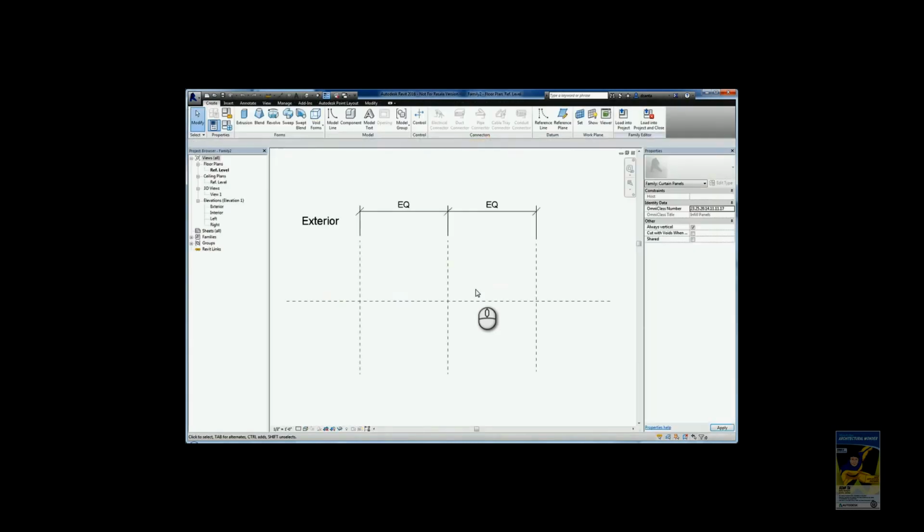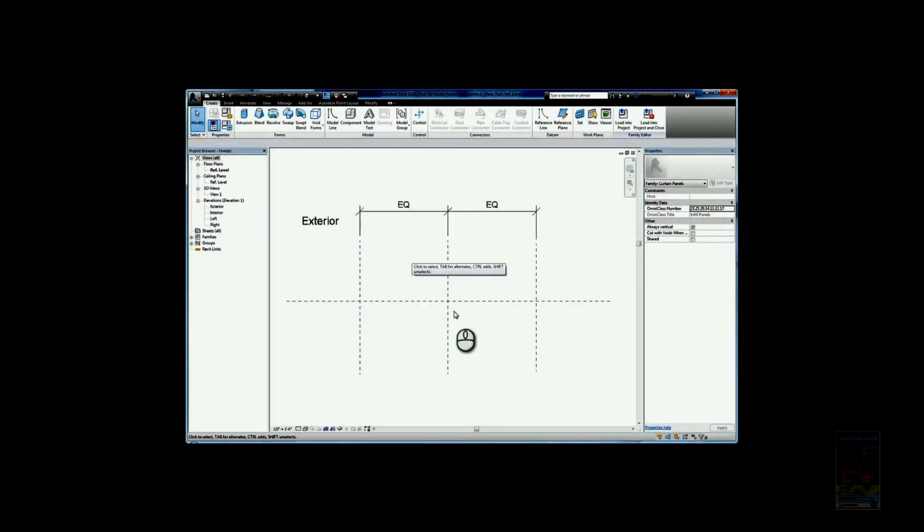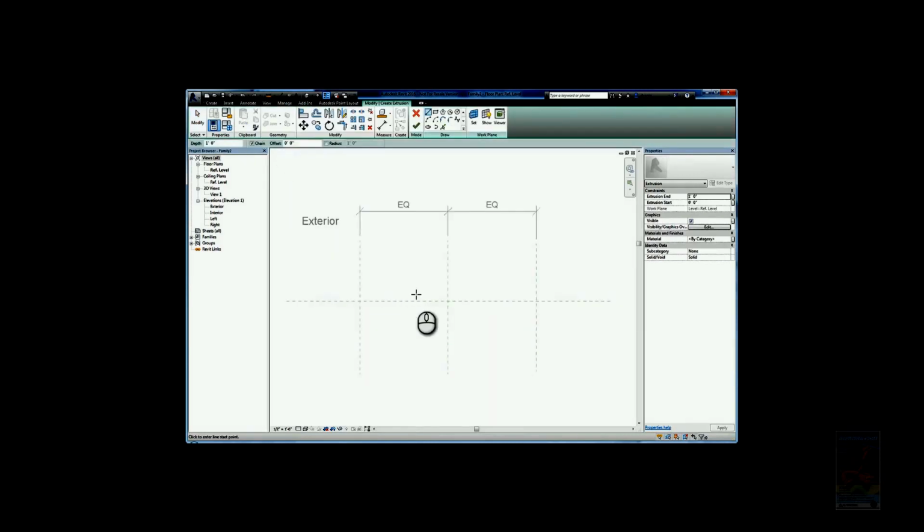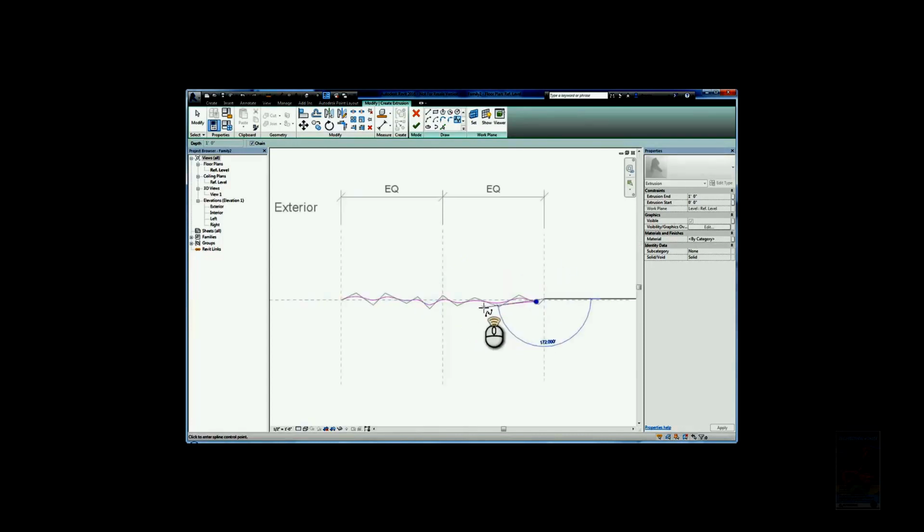It will open up, and here you see in plan, and your objective is, this is the exterior side, this is the interior side, draw a profile that is extruded vertically towards my face, and it will make it look like a corrugated panel. So I'll go here under extrusion, and I'm in sketch mode. I'm just going to roughly put something in. You guys can pull from spec manufacturer information and draw something a lot more exact. This is for the purposes of just getting something down.